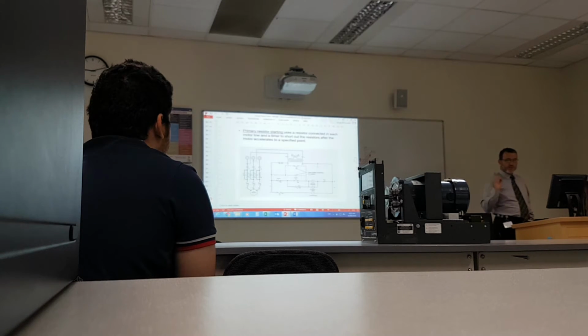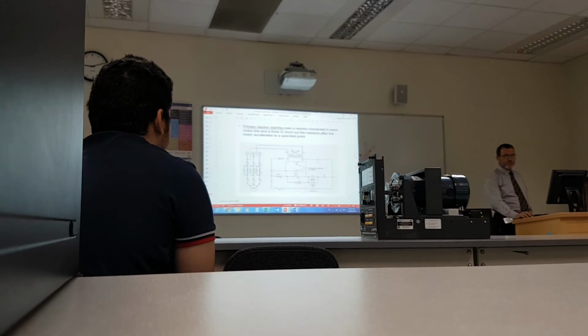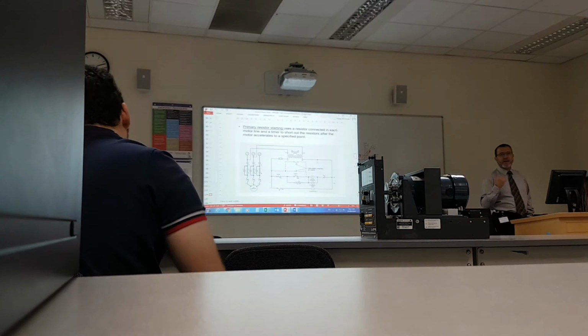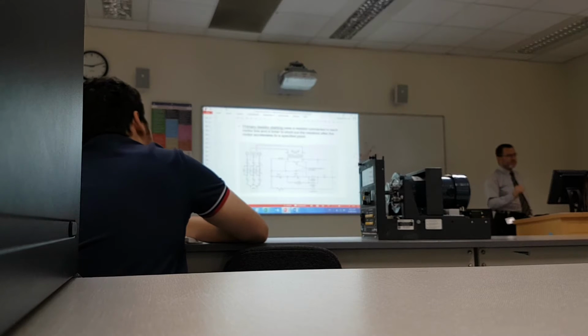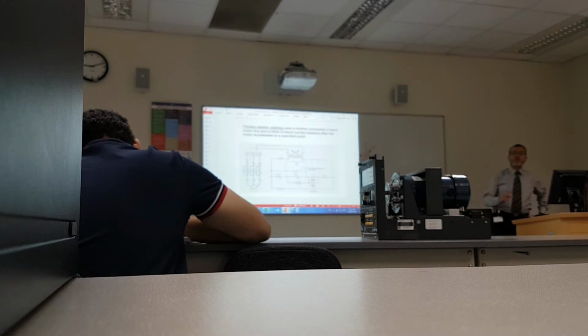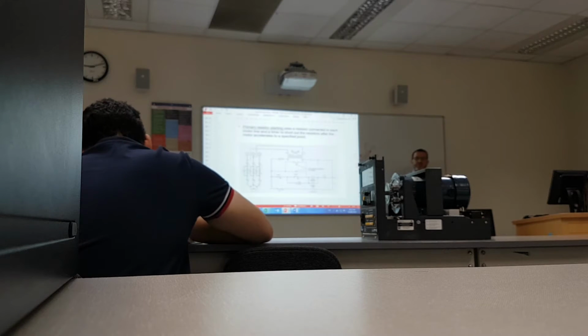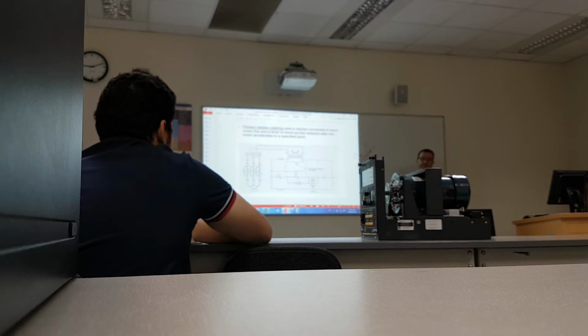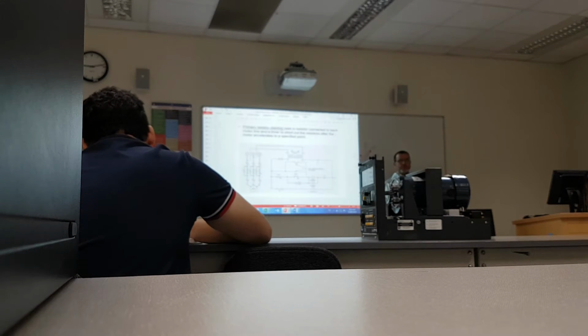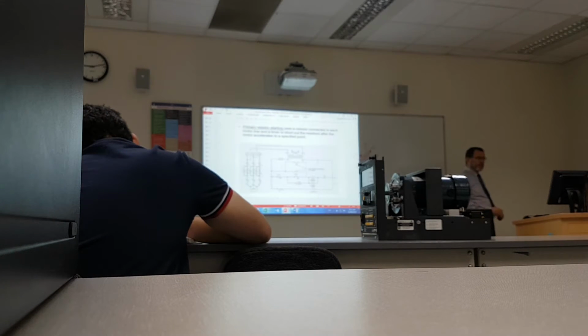All right, so this is the first method. Reduced voltage starting or reduced current. The primary purpose is to reduce the starting current. Again, when you talk about reduced starting current, what we're really concerned with is what? Voltage, with large motors. In small motors, it doesn't matter. It's just 6 times 0.5 amps, it's not much. Just 3 amps. But if you have a huge motor, like a 2.5 megawatt motor, that's huge. You need to be very concerned about the starting current, because it could affect the system.